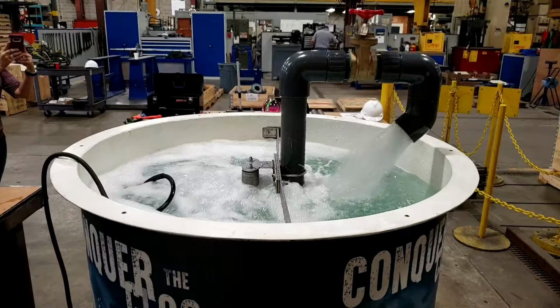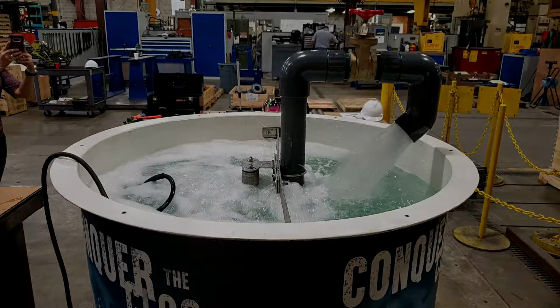Teams may attempt to troubleshoot and resolve the problem. If the problem is resolved, a penalty would not be assessed. If the pump needs to be adjusted at this point, you must turn the pump 1 and pump 2 HOA switch to the off position before touching the pump. Once you have adjusted the pump to your satisfaction, then turn the pump 1 and pump 2 HOA switch back to auto and hit the pump 1 start button. Communicate out loud, pump 1 is operational. You may repeat these steps as many times as necessary.